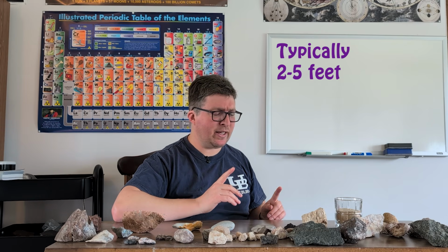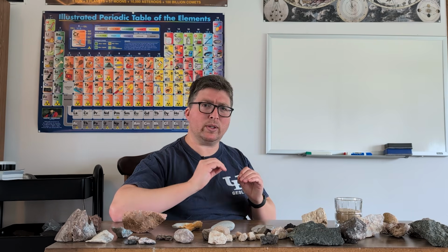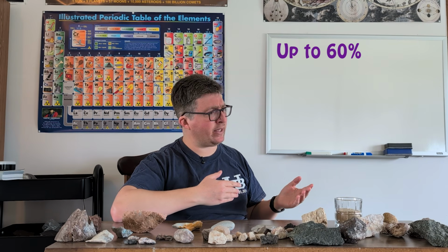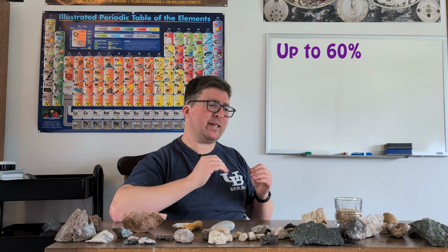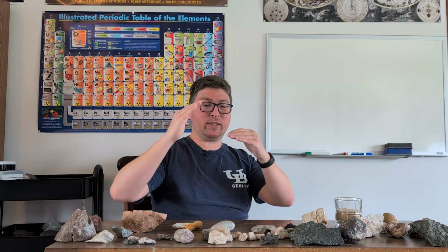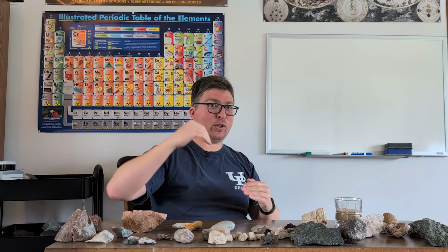Now, here's the thing. Clay can have a very high porosity. It can hold a lot of water. So why do they use clay to line these landfills? Well, because clay has a very, very low permeability and extremely low hydraulic conductivity. So even though there's a lot of pore space in between the tiny platy crystals within a clay, those tiny platy crystals tend to overlap and lock together and not allow the water to flow through.